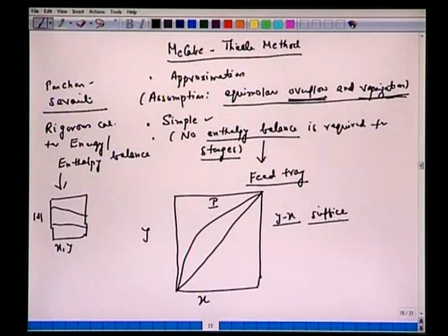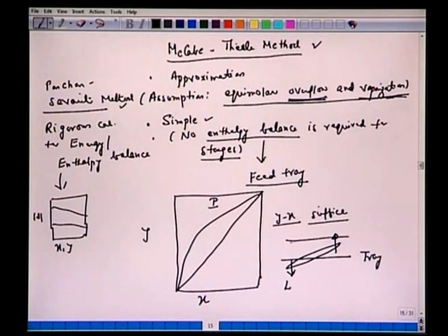Okay. So of course, in this McCabe-Thiele method, we have a similar story, that on a tray, the vapor leaving the tray and the liquid leaving the tray, they are in equilibrium. So this assumption of the two streams in equilibrium still holds good, either it's a McCabe-Thiele method or it's a Ponchon-Savarit method. All right. Except here, we make certain assumptions that this flow rate L is the same as what we have getting here. Similarly, the vapor phase flow G, molar flow rate, moles per second, is the same as the tray underneath this. All right.